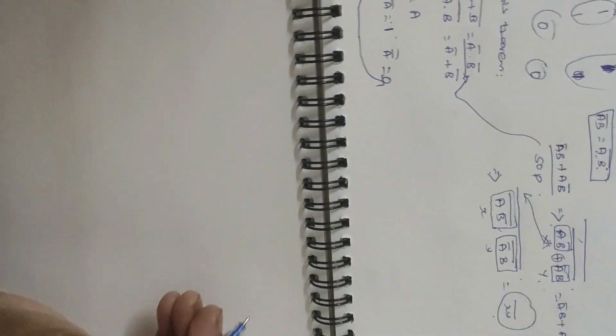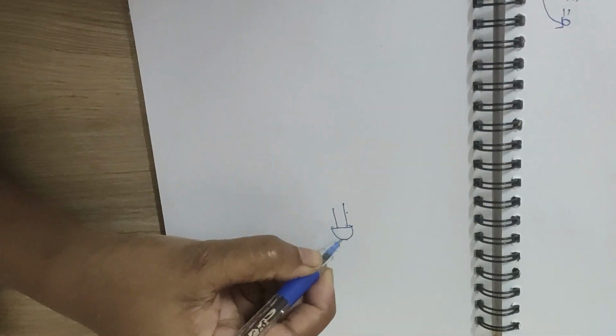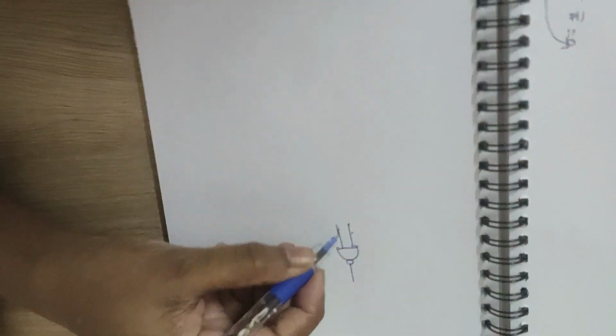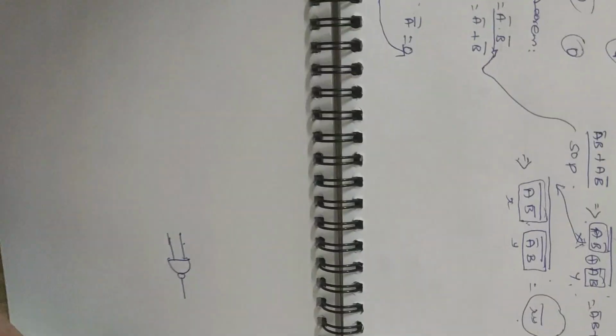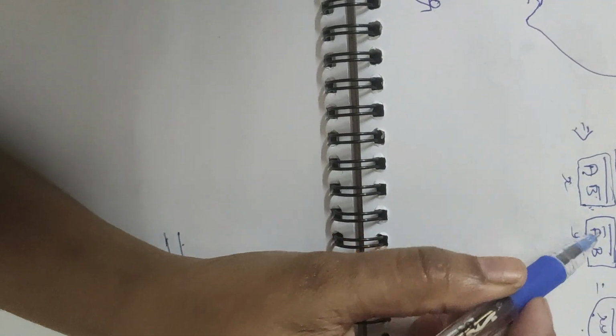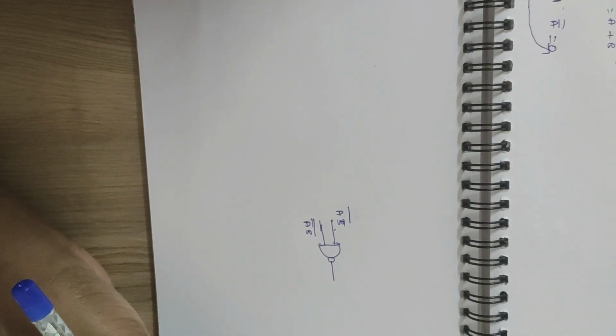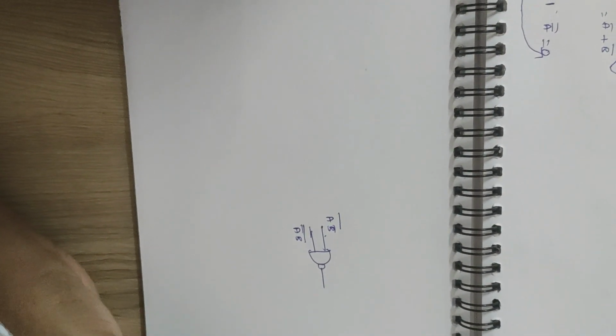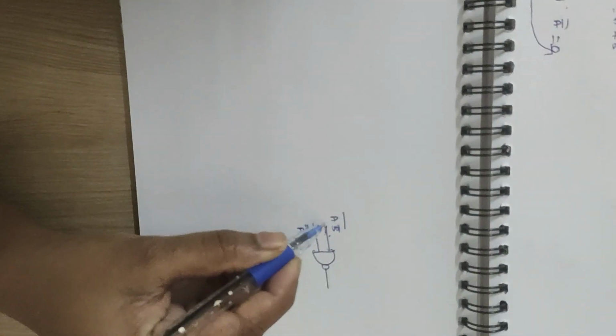So the first NAND gate is what we put at our output, as we have finalized. Here x is (AB bar)bar and y is (A bar B)bar at the output NAND gate. This is what we needed here.